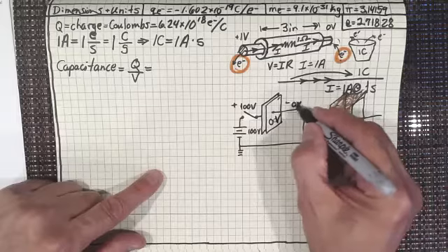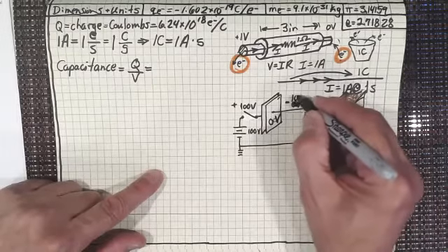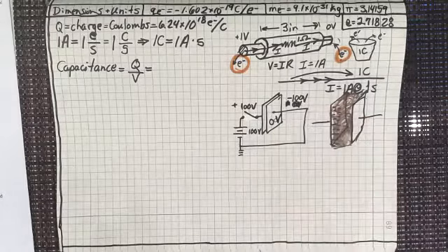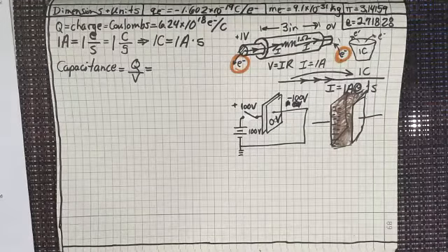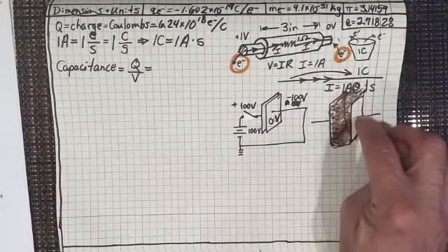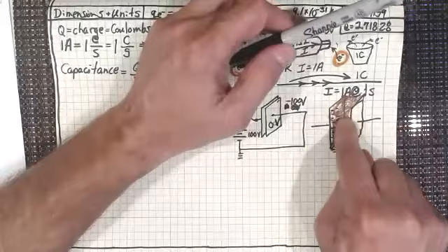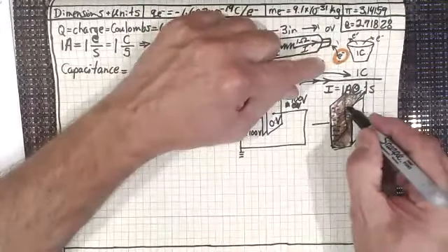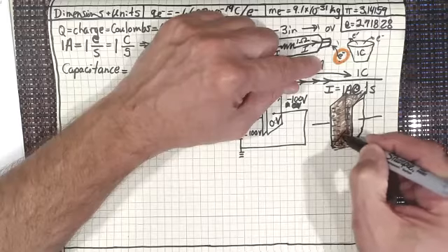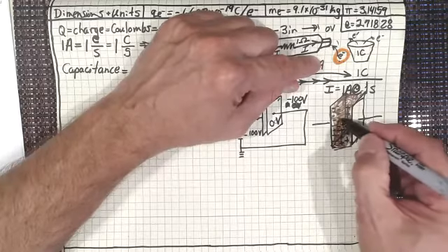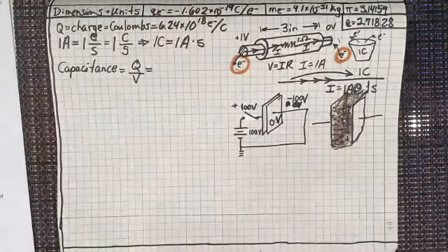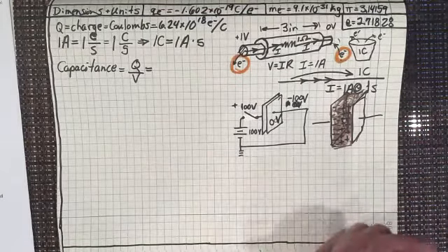In fact, instead of making that 0, why don't I make it negative 100 volts so that it really in your mind just sticks there. So I've got minus 100 volts on the other side connected to this thing right here. So I've got minus. And so what's that going to attract in the dielectric? That's going to attract a lot of positive charges in the dielectric to line up here, right? So there's never an electron that ever transfers through a capacitor. Now, the next thing I want to ask is, once I throw this thing, is there going to be current flow?